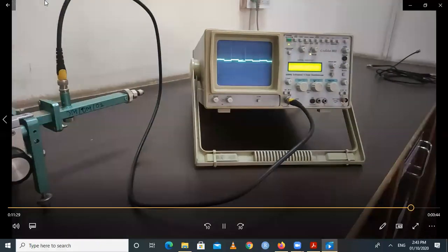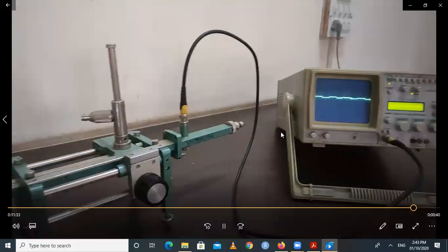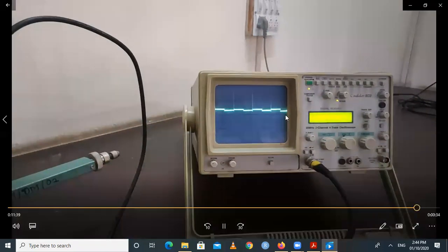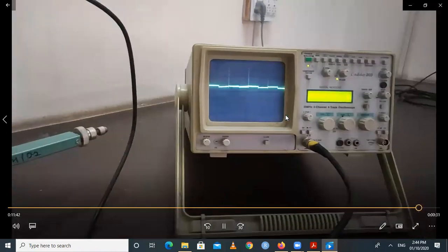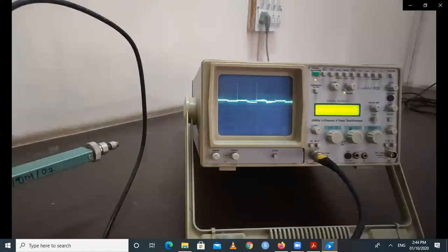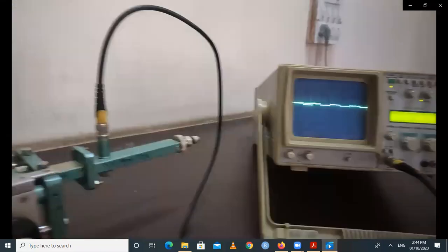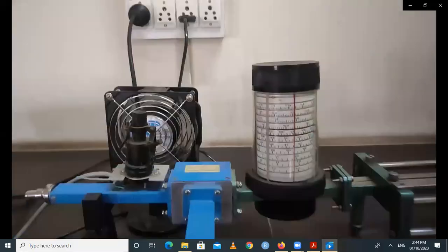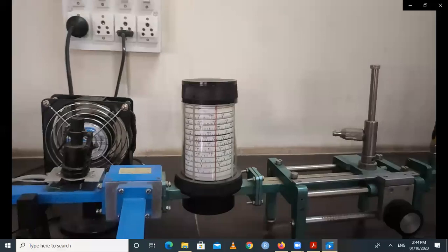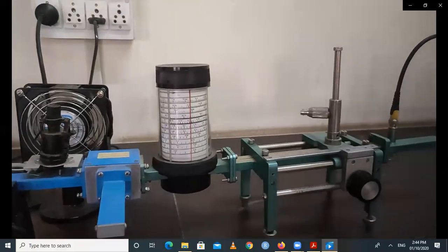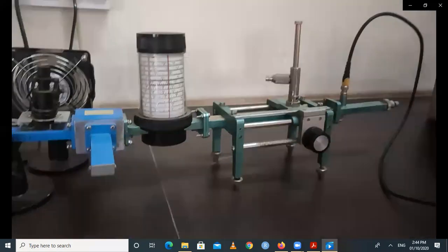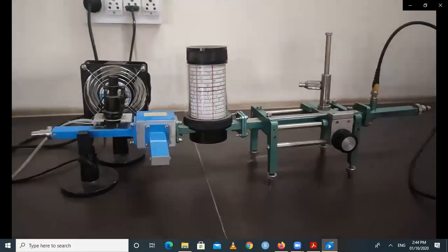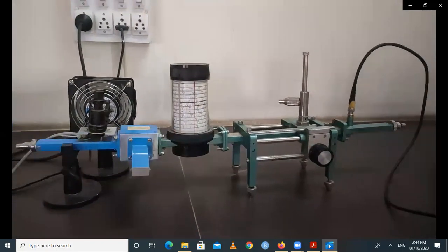So in this way, for each mode you have to find out these three values, means there are two minimum points and one maximum point, and for each point you have to find out the repeller voltage, frequency, as well as the output voltage. So output voltage you have to set to the x-axis, and you have to measure the output on y-axis multiplied by channel 1 value. So in this way you can find out the mode characteristics of Reflex Klystron, and this procedure you have to repeat for mode number 2 as well as mode number 3, and you are getting an output in the observation table. And finally you have to go for plotting a graph according to your observation values.